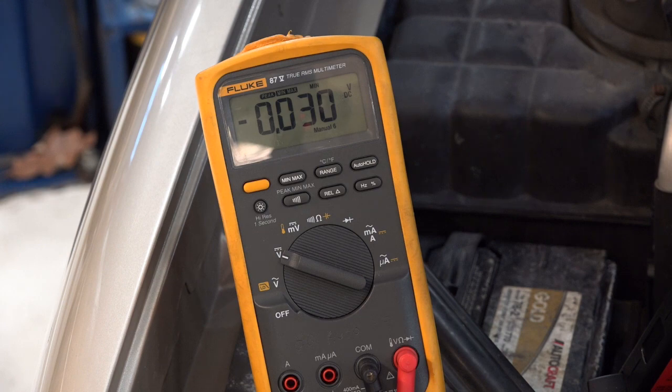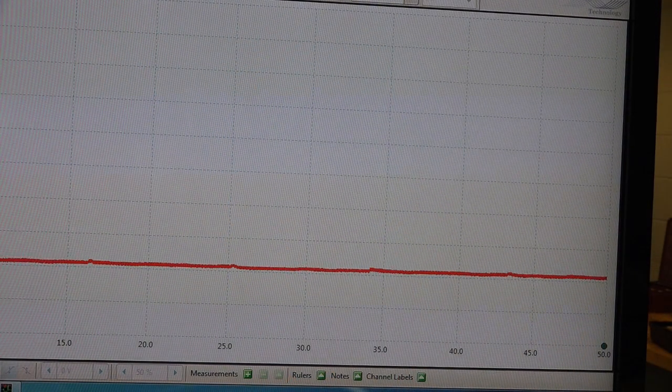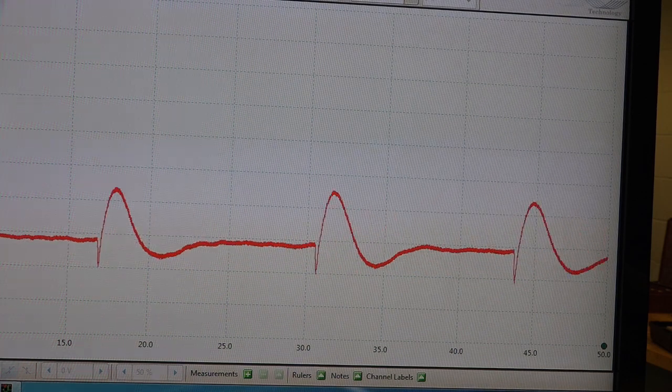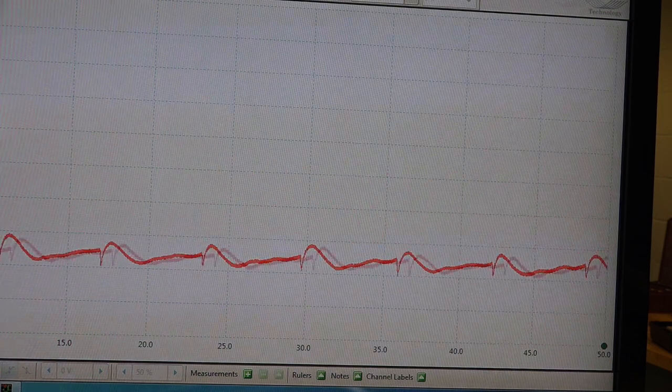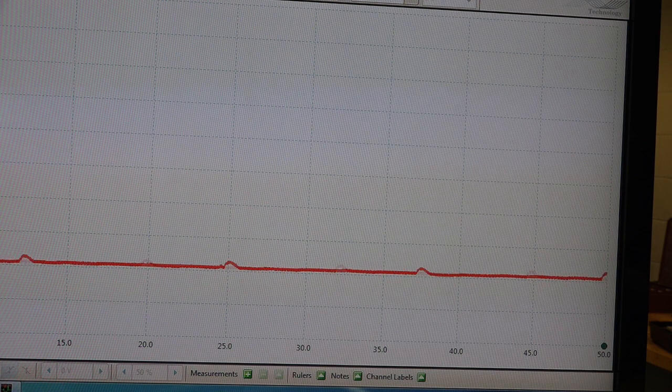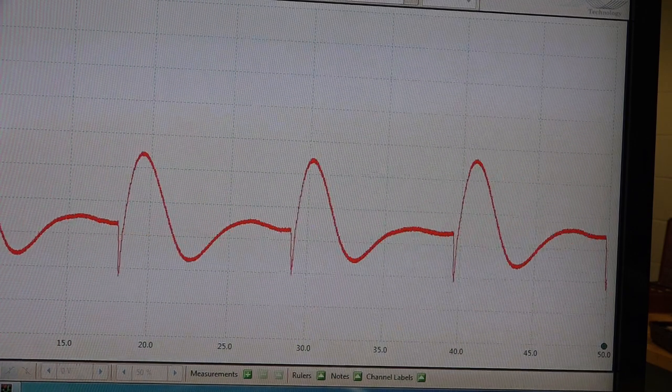on, again, the negative cable. Here's the current trace for the parasitic drain. We've got an increase of current occurring here. There we go. It's increasing. That was up over 10 amps. The pattern appears to be that of a brushless motor. Regardless, we'll look at this. I believe we've confirmed our parasitic drain here, matching the peak min-max of the meter.